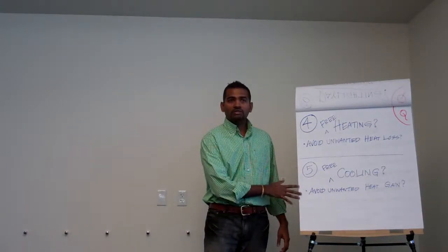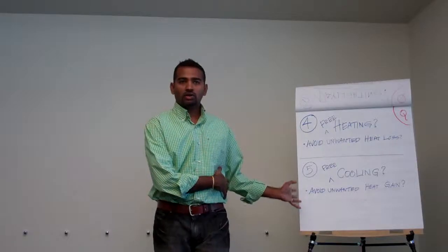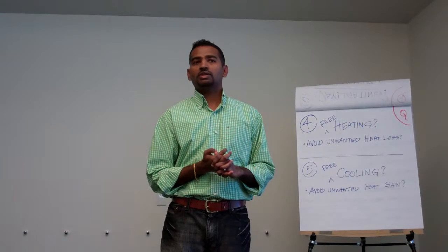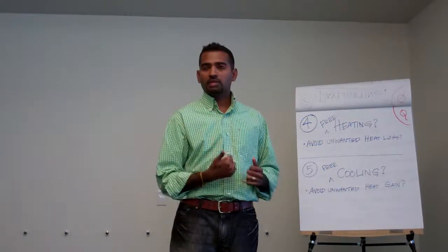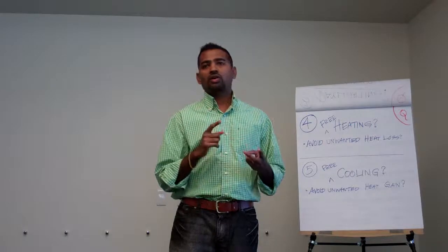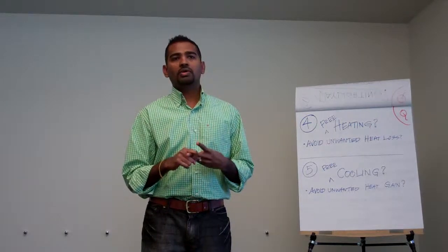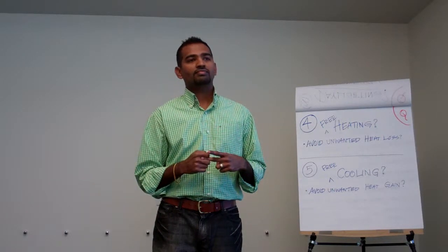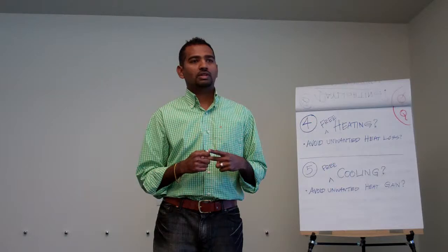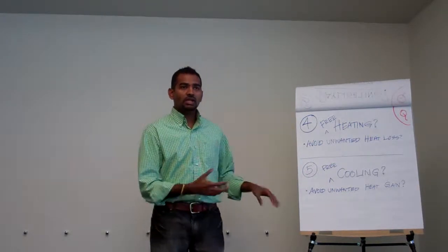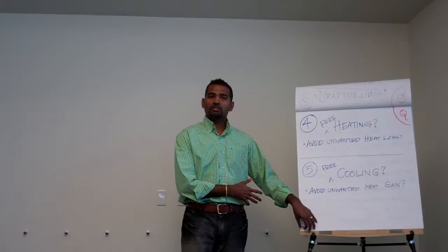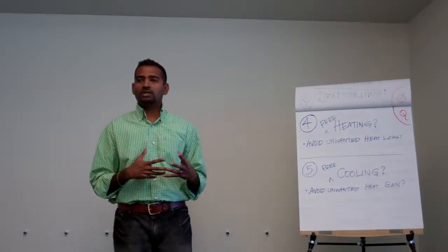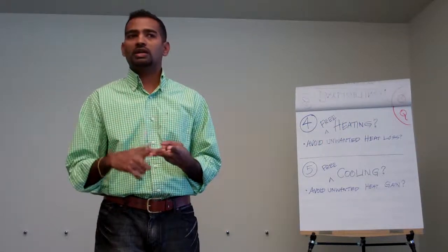And so likewise with the cooling, and I talked about this earlier, the simplest cooling strategy here is to have, we'll look at this in a minute, night flushing or direct evaporative cooling. How many of our clients will accept direct evaporative cooling? Only in very limited spaces. So it's important to ask that question, because we can show them that will be one of the heaviest strategies to reduce energy consumption. Are they willing to take into account maintenance and the other things?